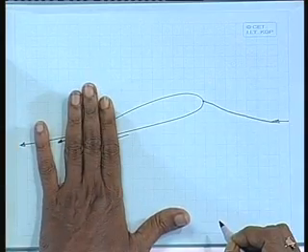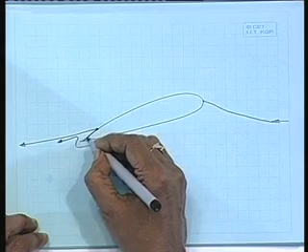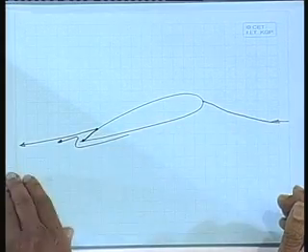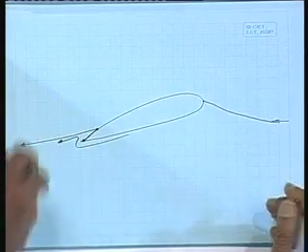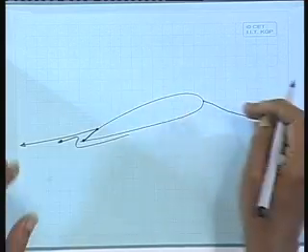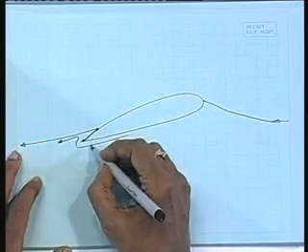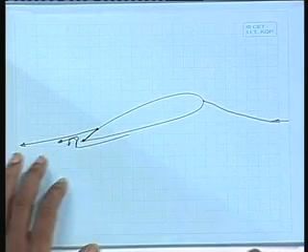This is unsteady flow. So, the steadiness of the flow will come if the stagnation point moves down here. That means, this flow will go like this and that flow will go like this. You can see here what is happening. As the flow starts, because of the pressure distribution, there will be a stagnation point here which is unsteady, and as soon as the flow starts there, there is a rotational velocity being imposed.